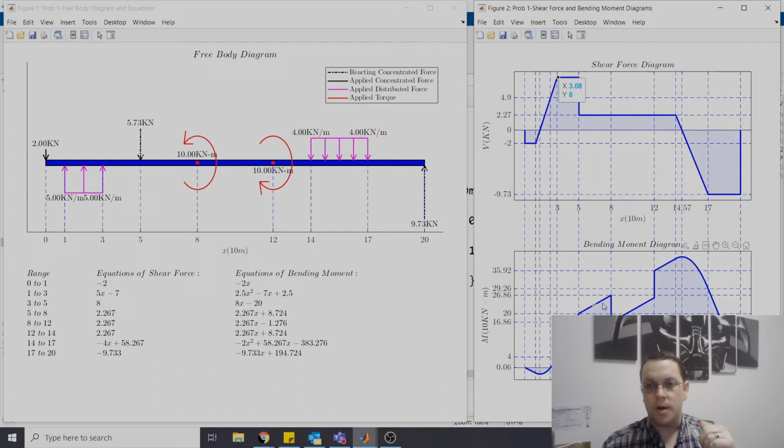So this is going up and up until here at about 8. What's happening at 8? This is right where you're applying the torque, so you would expect it to be very high at that point. You'd expect a local peak because that's a high stress concentration point. Then you come down and go the opposite direction at 12. The overall magnitude is still rising, and your average is going to be somewhere around 29.2. There are mathematical reasons for that. We're not going to get into that now.